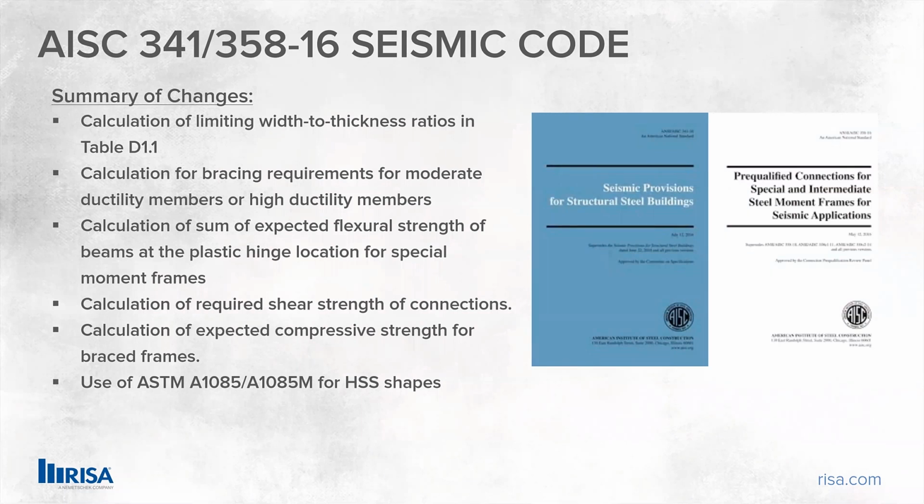Also, the calculation of the required shear strength of connections, the calculation of expected compressive strength for brace frames, and then ultimately the implementation and full acceptance of the ASTM A1085 specification for HSS shapes, now included both in the AISC 360, but also in the AISC 341 and 358 conditions.